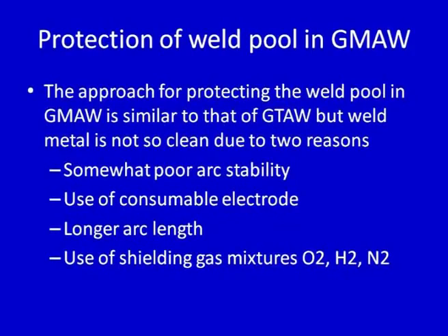while in the case of the overhead position welding, where helium tends to move up, even a low flow rate of the helium will be good enough, because it will be trying to move up and will be forming an effective cover around the weld zone. Then, the protection of the weld pool in the gas metal arc welding process.